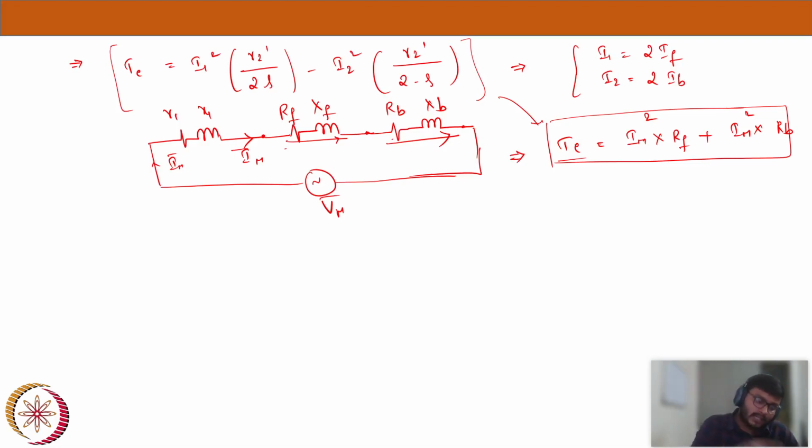When we started the discussion of the single phase induction motor, we started with some notations, and we drew some conclusions about our single phase induction motor: that it does not have any starting torque, right? Because there is only one winding and there are no two forces in quadrature with each other, and that's where we found the need to introduce another winding. So to check whether this equivalent circuit is exact or not, we can verify this equivalent circuit at the starting. At the starting, we know we should not get any torque, right?